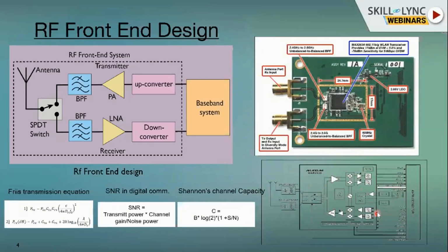In a similar way, if you look at the other side, that is the transmitter part. It comes from the modulator part. From the modulator, it goes to the local oscillator, and from the local oscillator, it goes to the power amplifier. The power amplifier, as I mentioned, sends a signal over a long distance. But when you go for very high frequency, the distance will reduce. Your GSM frequency works at a longer distance, while Bluetooth or Wi-Fi have a strong channel capacity but limited coverage.